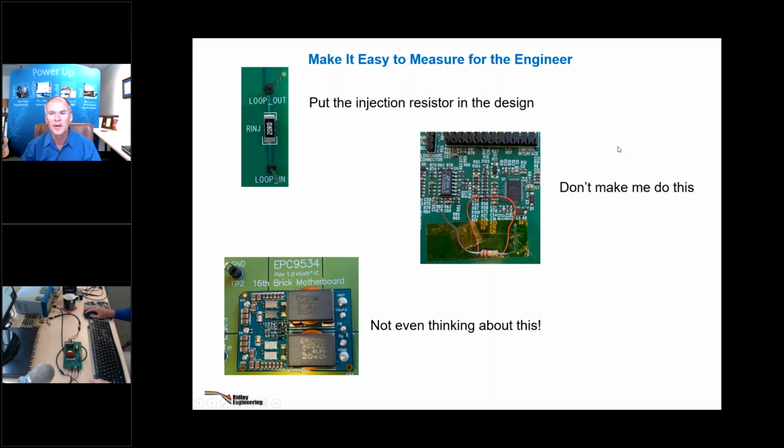Why 20 ohms? Or 50, or why 20 ohms? Well, most analyzers have an output impedance of 50 ohms. So if you put a 50 ohm resistor in there, you'd get the maximum signal from it. However, if you put 50 ohms in there, you're going to disturb the set point a little bit. So 20 ohms, 10 ohms, it's not really that crucial, quite honestly, what the value is, but 20 ohms is just kind of a sweet spot in there. 100 ohms is definitely too much.